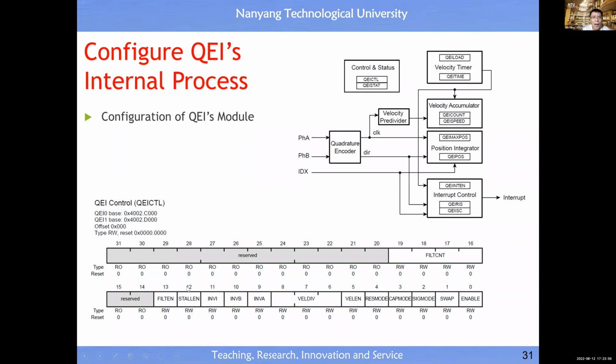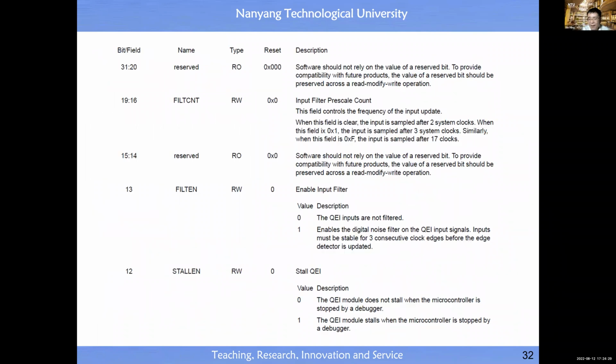This one is for your software to do the setting. That means if you debug your hardware, you temporarily stop your machine and stop your sensor, but don't lose the data. Inverse is basically for the reference pulse. You can change from negative pulse to positive pulse. Signal B can change from positive pulse to negative pulse. Signal A just inverts the meaning. All this has been explained here.